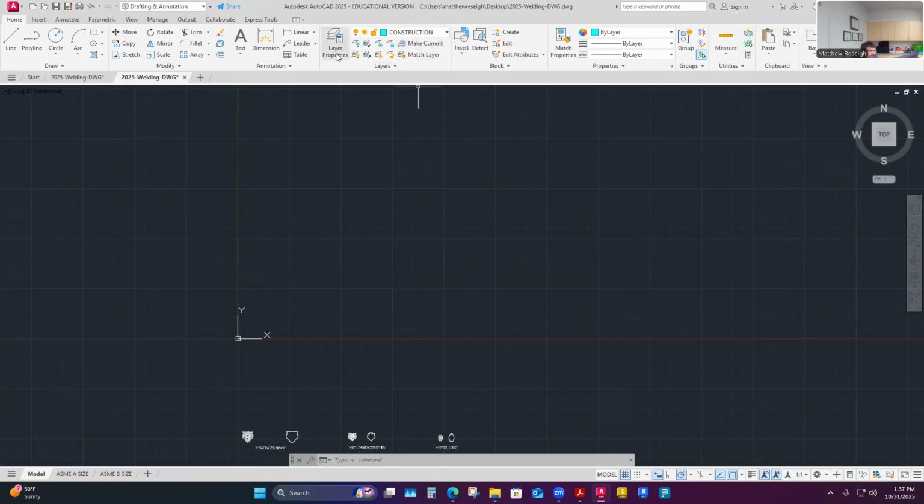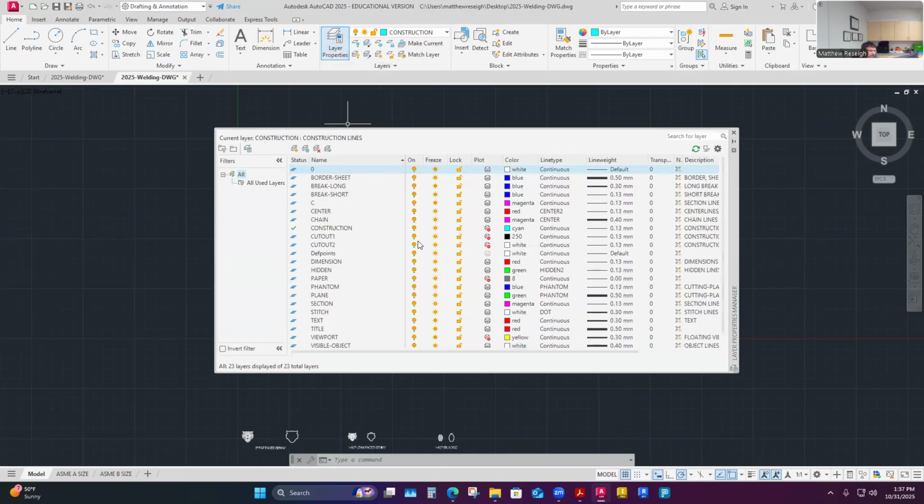So what I've provided you is, if I click on this button, it shows you what all layers I have. It's a way I manipulate and change layers, or add layers or delete layers. You wouldn't have had anything on here in a default template. All you'd get is layer 0 if you opened this, or if you've downloaded this from your home and open up a drawing file or even a DWT file, it's going to come with no preloaded layers. It's just default, just to have a layer 0, and then it's made to build layers for what your specific needs are.